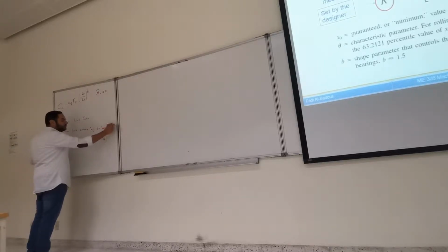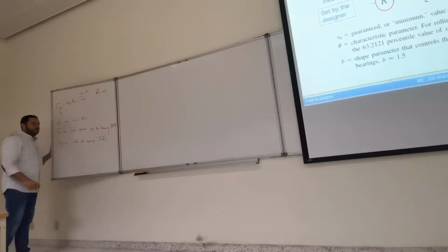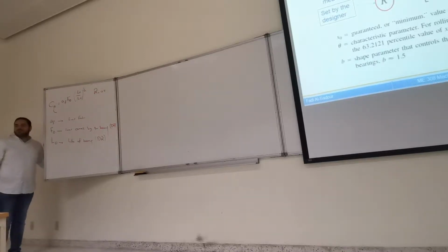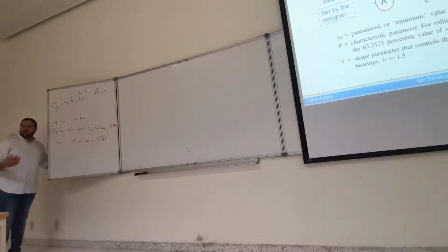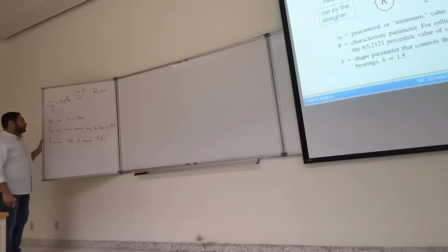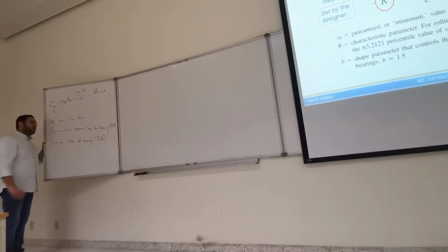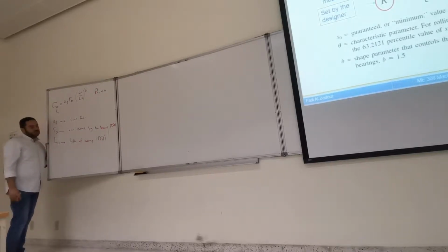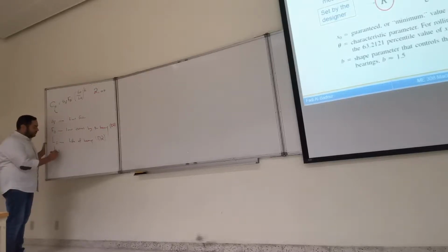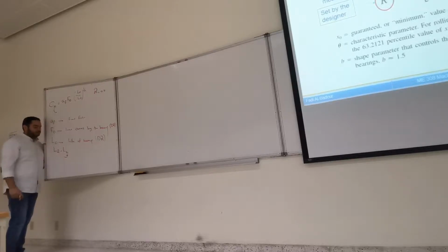Based on the design, the loads on the machine, you calculate the reaction loads, etc. You get the loads on the system, and the life of the bearing is based on how long you need the bearing for that. LR is also called L10, and 10 here again is the probability of failure.